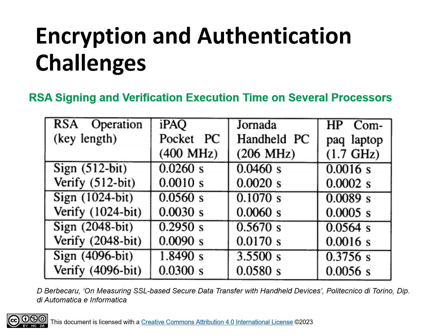This table shows the signing and verification times using the RSA algorithm with different key lengths at different processors. Any key shorter than 1024 bits is considered too weak to protect the system. As depicted in the table, the signing and verification process takes more than 4 milliseconds, allowed by the IEC 61850 standards.